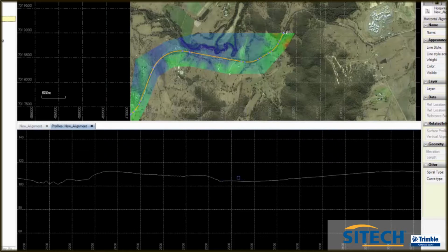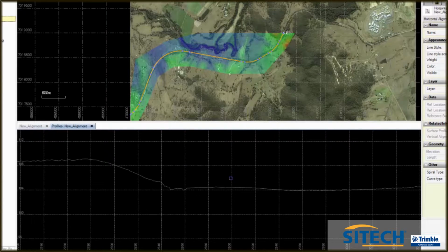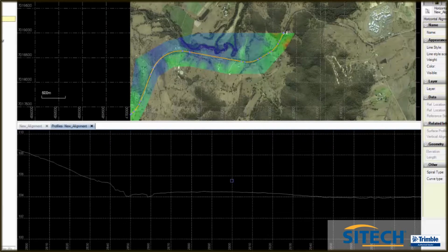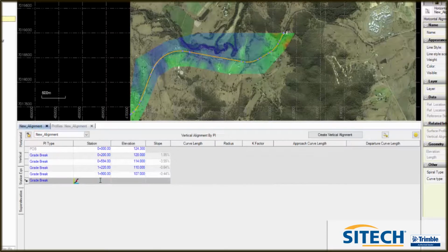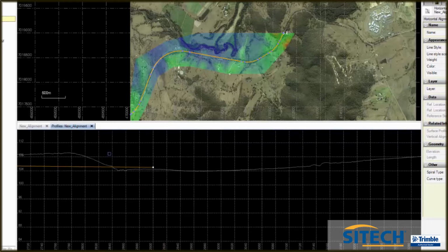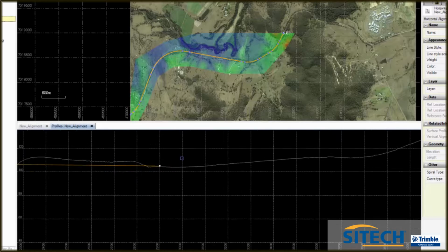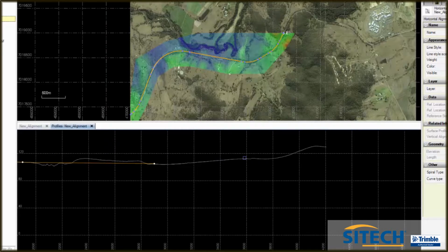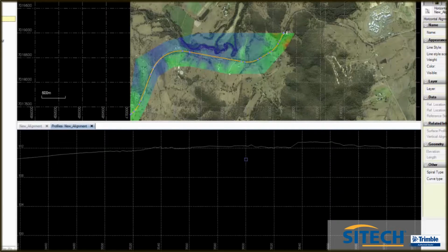Looks like the next one should come through to about here. So we'll go 2900 and 105. These ones get edited, particularly when you're calculating earthworks volumes. So the less earth we'll have to move, the better. So it's starting to go uphill here, and it climbs even steeper at the end there. So we can put it a little under there, at 3600 and 107. So enter that.